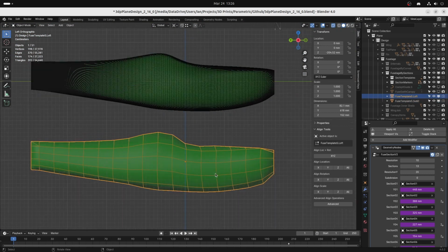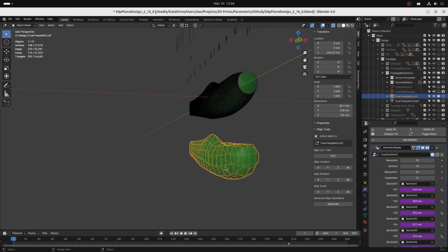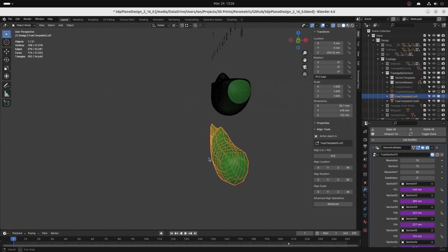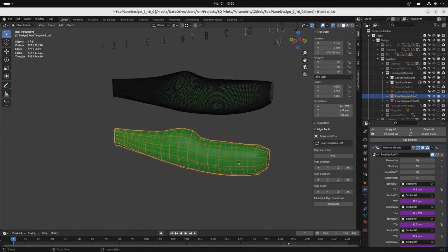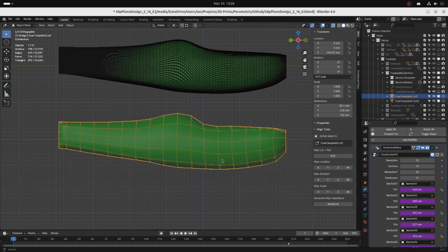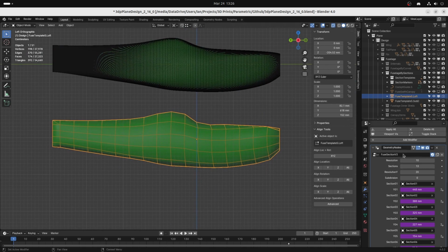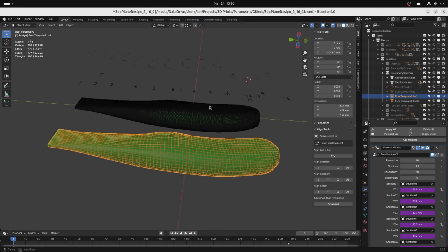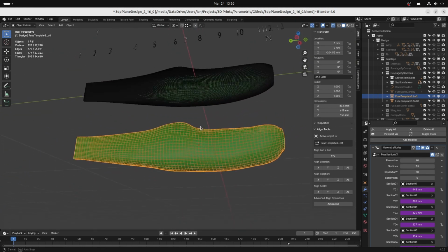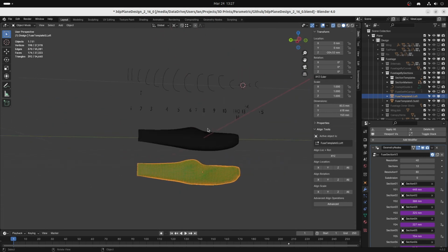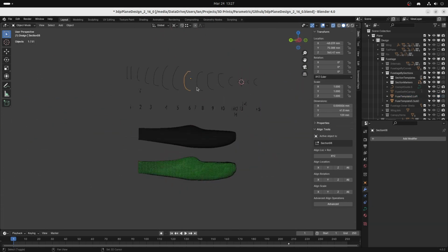The second option is called Fuselage S Loft. Effectively, the function fits Bezier curves along the length of the fuselage, and this means the shape of the sections is accurately preserved, and the resolution can be set in both dimensions, both radially and longitudinally. One downside to the Lofted version is if you have two sections close to each other, they must be very similar or the end result won't be smooth.